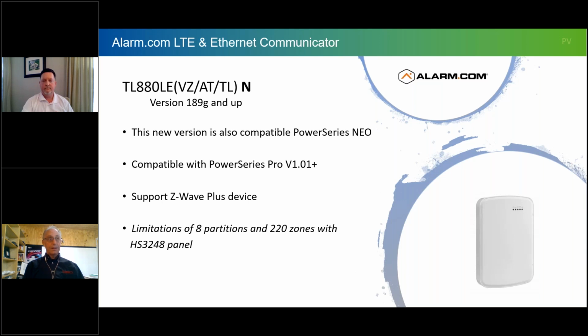It does have the Z-Wave controller built in. A little note in there, in case you're using the 248 zone panel, just mind that you have a limitation of 8 partitions with alarm.com and up to 220 zones with the 248 zone panel.